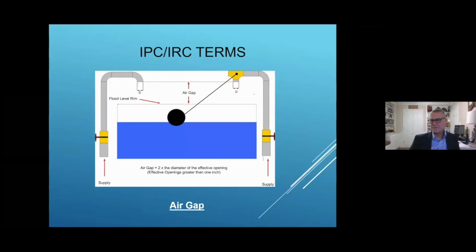The first one is an air gap, and that's probably the most foolproof because it involves vertical free atmosphere. So you can't really break that, and it doesn't really stop working. You'll notice the big rectangle with the blue and white areas in it, and the black dot in the middle. That's a vat or a storage tank, for example.